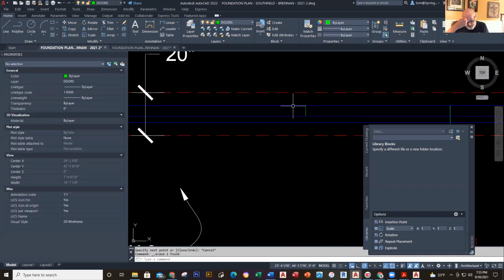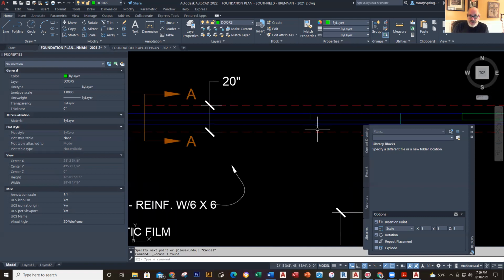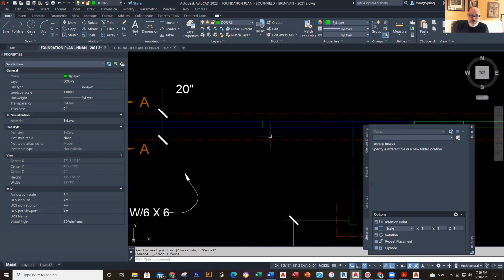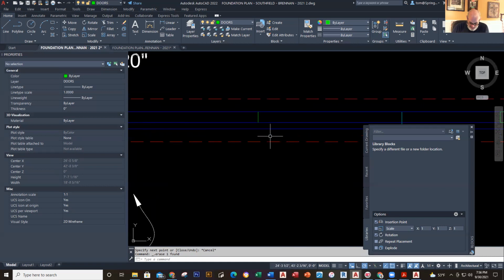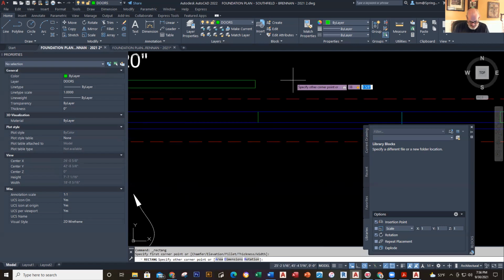All right, and that's where I want the next one set up. So I got this runway here as my marker. And then what I would do is, since that's a 5-inch wall, I'd make them 2.5 inches by around, oh gosh, whatever, 6 feet. That's like 36, 38 inches. Okay, so I'll just do this. I'll make a rectangle, and I'll make it 38, comma 2.5, boom. Okay, and there's half.